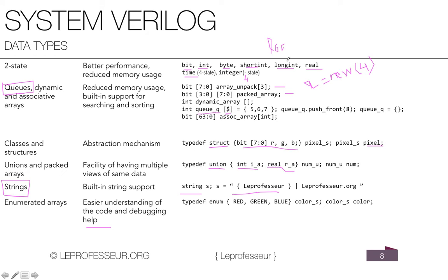So logic types are similar to register and wire. The difference is that your register or your wire can be driven by multiple nets. But here, say if you want to find out the bugs in the netlist, whether a signal is driven by multiple drivers, what you can do, instead of using a wire, is use a logic, and your simulator will print out an error message, because logic type cannot be driven by multiple drivers. Okay.